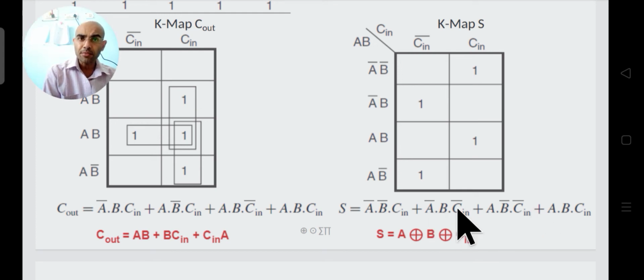If you want to implement the expression with the help of our basic gates, then we will require this expression for sum. Carry is no problem, but for sum we will require this. If you use the simplification technique, you will get XOR gates, and XOR gates are not basic gates. That is why we have written the expression in this form also. At first, I will tell you to implement the expression with these gates, but later on for further implementations we will use the XOR expression. This expression is more important, but just to realize the circuit with basic gates, we have written this expression also.